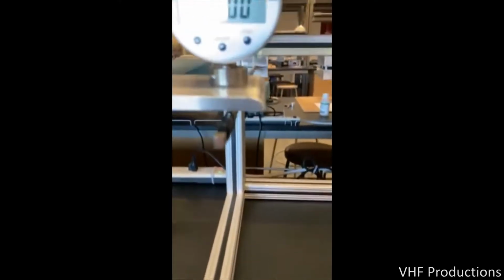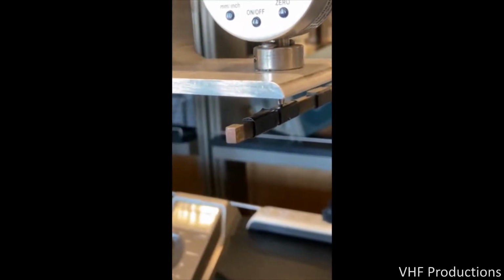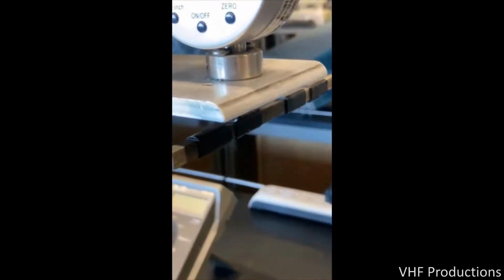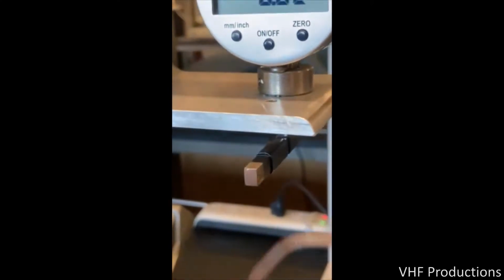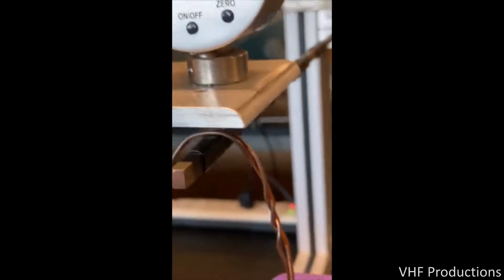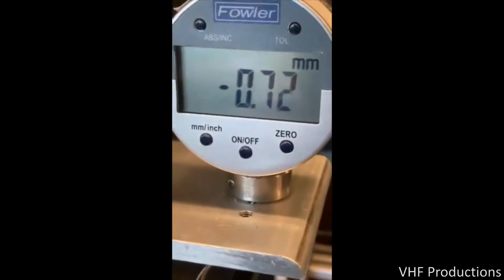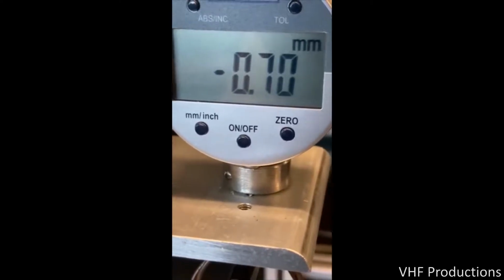In addition, for each load condition, meaning 1 kilogram at each of the 4 load positions on each bar, we're going to also measure the strain of that longitudinally oriented strain gauge mounted on the top surface of the beam located at the hinge point where the beam attaches to the frame. So each measurement consists of a load, 1 kilogram, at a length L, with a displacement being measured by the displacement gauge and a strain being measured by a strain gauge.